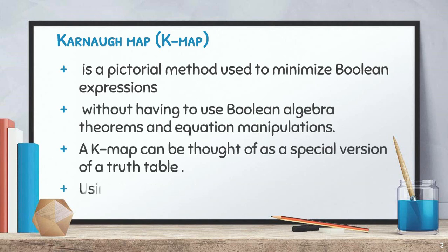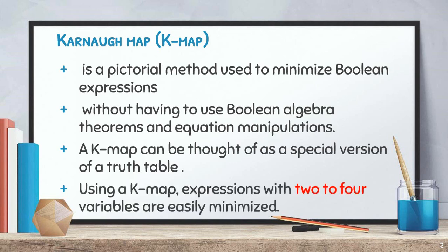The K-map is a matrix of squares. Each square represents either a minterm or a maxterm from a Boolean equation. The arrangement of the matrix squares performs identification of input variable redundancy, which helps reduce the output equation.